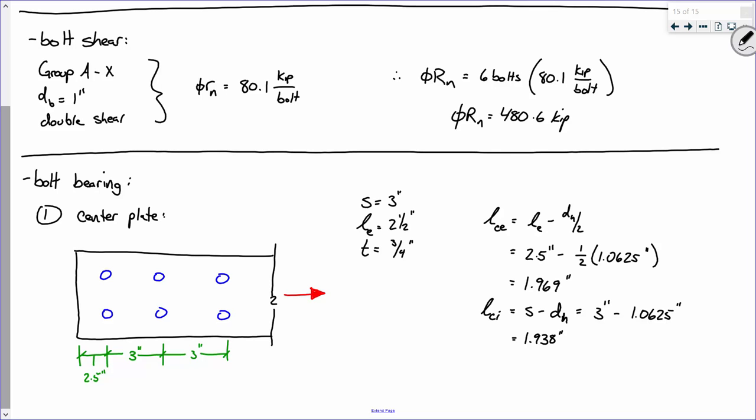The best way to answer that is because staggered connections can be laid out in any different pattern. You measure along the line of where the load's being applied. So we are measuring edge distances this way because, if we're looking at an interior bolt, so here's our interior bolt, the center spacing is 3 inches, but the clear spacing is 3 inches minus half a hole diameter minus half a hole diameter. But that distance, we're measuring it this way because, think, if I'm yanking on this, right, or actually, I have to be over here.